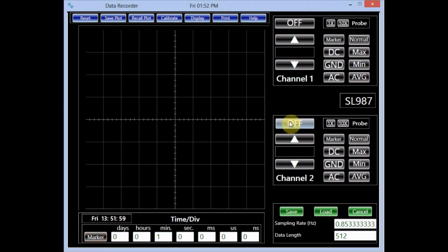Let's review the signal on channel 2. This signal is the output of a temperature sensor. Since we are using a coax cable to connect the signal to this channel, the 1x scope probe setting must be used. Since temperature does not change rapidly, the sensor is stimulated with a 60 watts light bulb at a distance of about 2 inches.